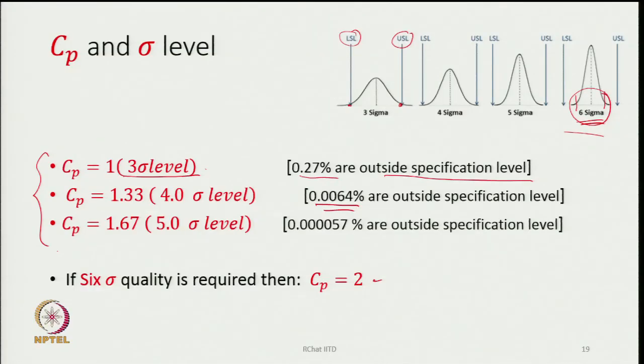In our case, even a Cp value of 1 itself is something very good, but usually Cp may go below 1, it could be 0.8, 0.6, 0.7. So, we produce more defective material, which will go beyond the specification limit. Anyway, that needs a detailed discussion on 6 sigma; some understanding of 6 sigma is important here.